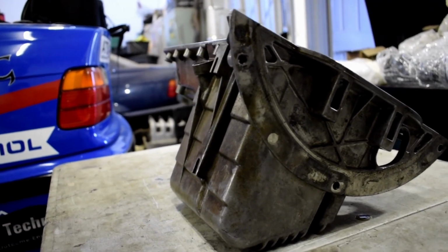That kind of helped me identify the sloshing effect, and that is exactly what I think is happening. So we know through the data that we go from oil pressure to no oil pressure. We've looked at the simulation. I need to understand why it's doing it. So I took a look at the design of the sump, the design of the baffling system we have.